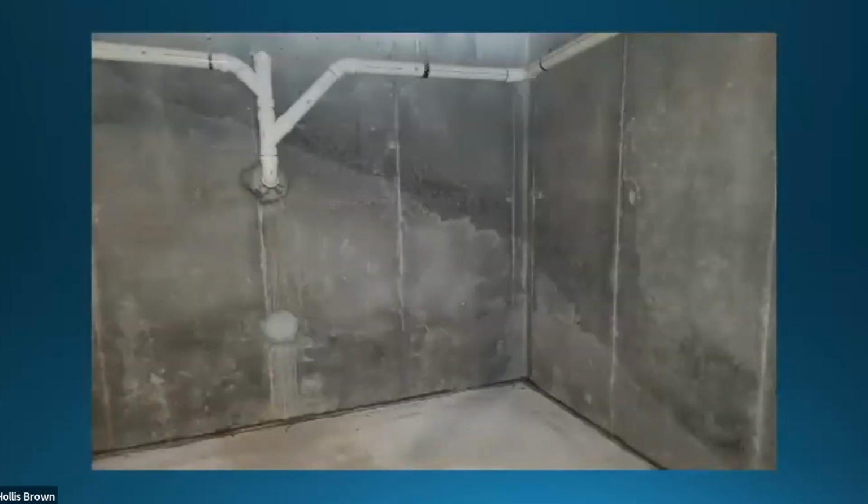Okay, we're into formed concrete. Concrete, when you have forms with reinforcement, becomes a much tougher task because that reinforcement makes it really hard to get your concrete in all the way down to the bottom of the footing and up through the form. And we use vibrators to make sure that happens. So you've got to pour the concrete a little wetter than you'd like to because you can't ram concrete in 8 feet of forms either. So it's just vibrating, but you can vibrate too much too.